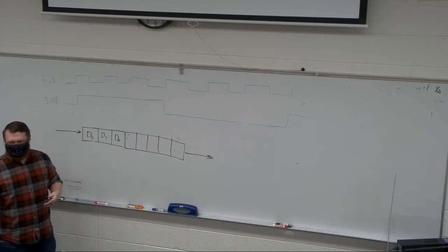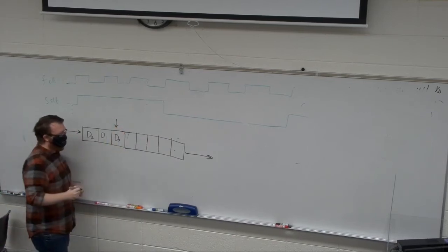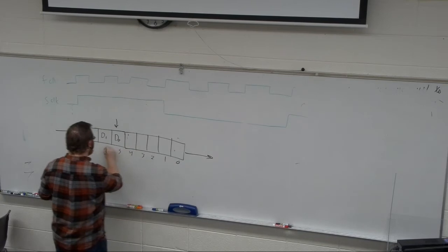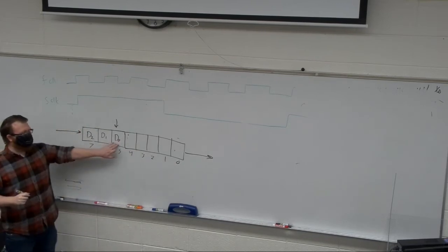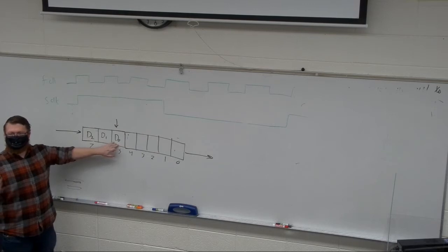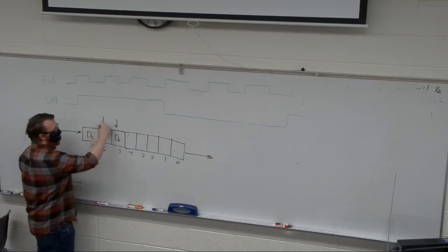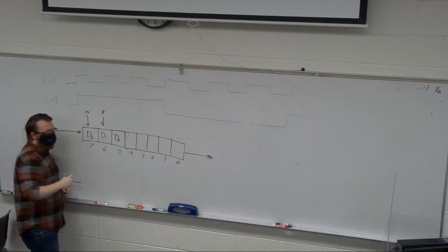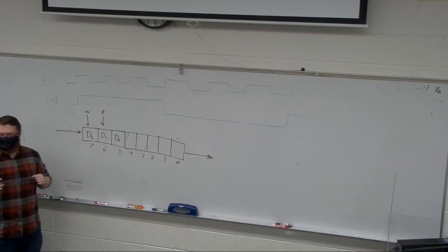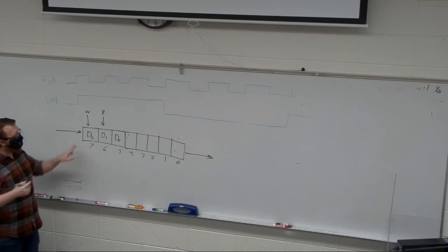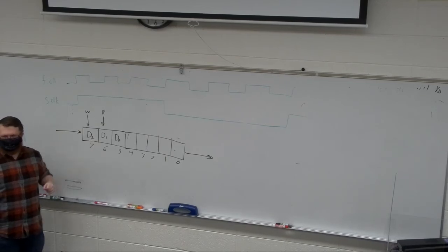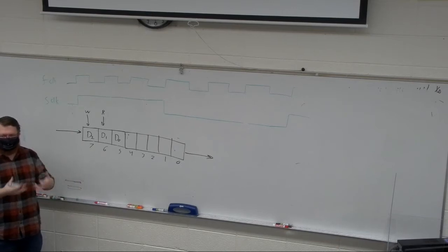So my read pointer starts here, right? I'm going to just number these for a second: 0, 1, 2, 3, 4, 5, 6, and 7. So my read pointer says I'm at 5. I read and then update my read pointer to 6. So read, write. Now if I add 1 to my write pointer, it just folds back around, because 1, 1, 1, sorry, this is just 8 bits. So 1, 1, 1 plus 1 is 0. It doesn't store that overflow bit, so it just wraps around.